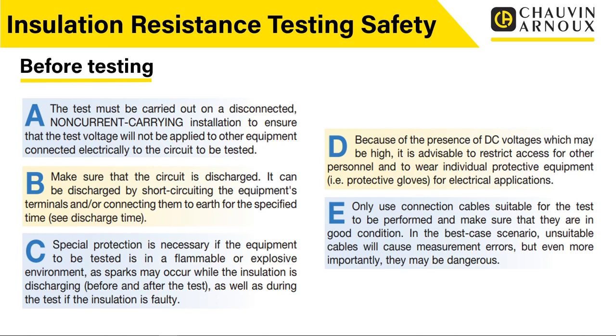So again, this is an important procedure, and when we start talking in the next webinar a little bit about the sort of high voltage testing, you will see on here that when we actually apply these test currents, equipment can become charged up to the voltage, and it can store that voltage unless it's fully discharged. It's the same when you're actually carrying out tests on circuits. Those circuits have been operating at mains voltage, so if there is any capacitance in there, capacitors, things like that, they will actually store that charge. So before we carry out the test, it is essential that we make sure that the circuit under test is fully discharged.